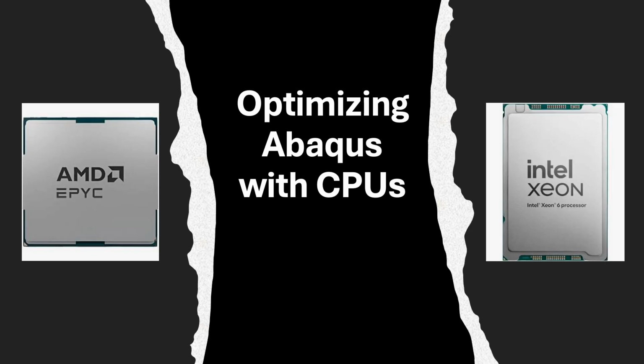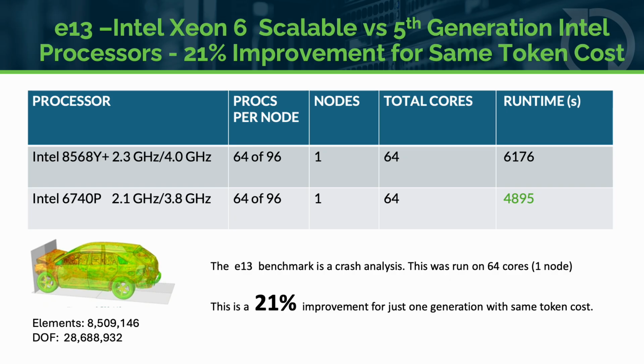Now back with Abaqus, again, CPUs are a core piece of solving any kind of application. And so picking the right CPU for the type of application you're doing is kind of important. But a key takeaway is, for the most part, always running on the latest hardware is going to give you a better performance. So in this case, we're going to take E13, and this is very much a memory bandwidth bound problem, and newer processors have better memory bandwidth.